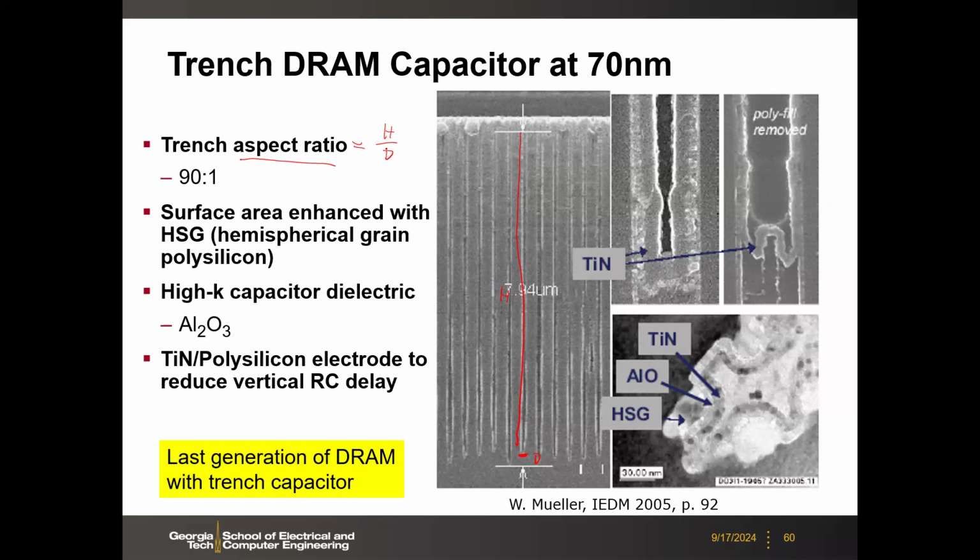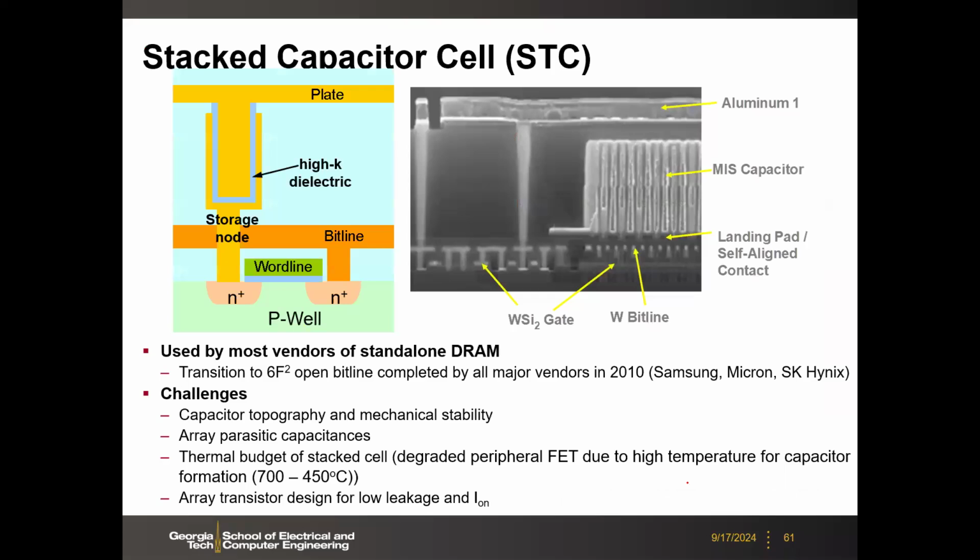So then high-K dielectric was introduced at that time. So this is the last generation of the DRAM trench capacitor in the year 2005. And after that, the industry switched to this stacked capacitor cell. We talked about that before, right?